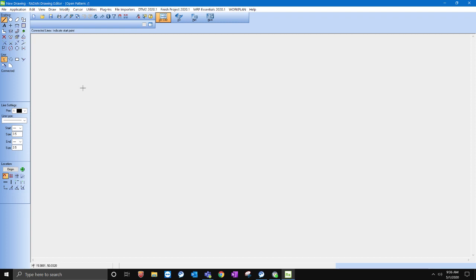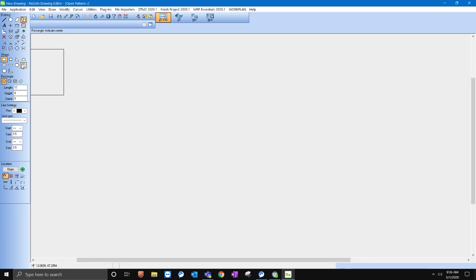Then you have the parametric side of it, so you can set up the parametrics where you add dimensions and everything based on numbers. If you have a spreadsheet set up with parametric values, you can plug in the values and it creates all your files, and away you go. This is good if you're getting into ERP systems, because you can output some of the data from the ERP systems and it'll automatically create your parts.